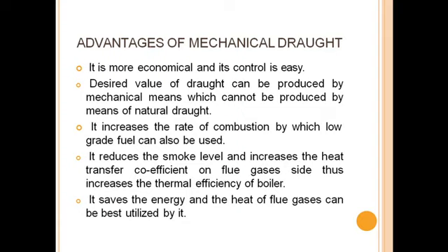Some of the advantages of mechanical draught: it is more economical and very easy to control, and the desired value of draught can be produced by mechanical means, which cannot be produced by natural draught. Third, it increases the rate of combustion, by which low grade fuel can also be used.